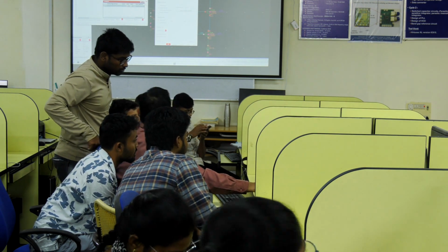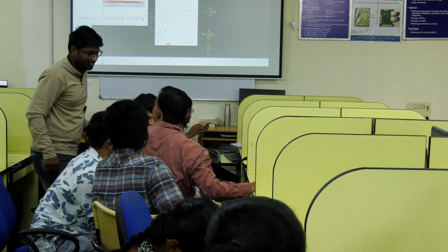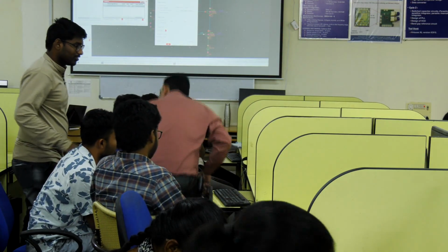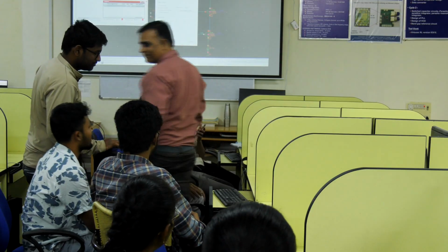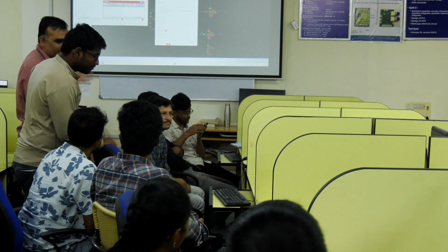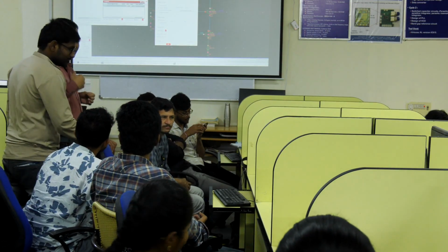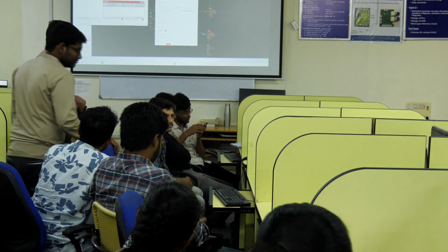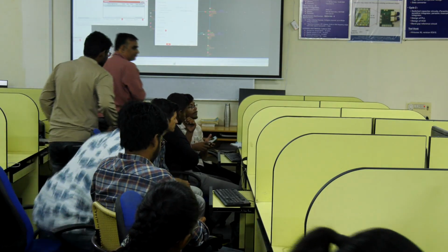At least you have got a DRC free circuit. I think we can let him go home, right? Not the best circuit, but the foundry will not reject it. I know there is no ground contact, but once the whole chip is made, there will be a ground contact somewhere anyway. So in a pixel, often we don't give ground contacts. It just takes area.